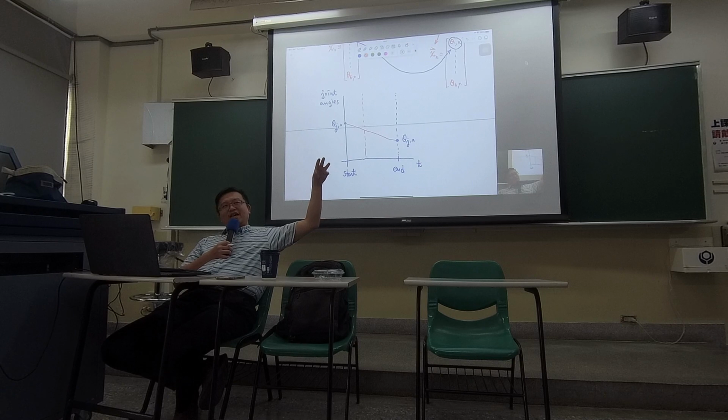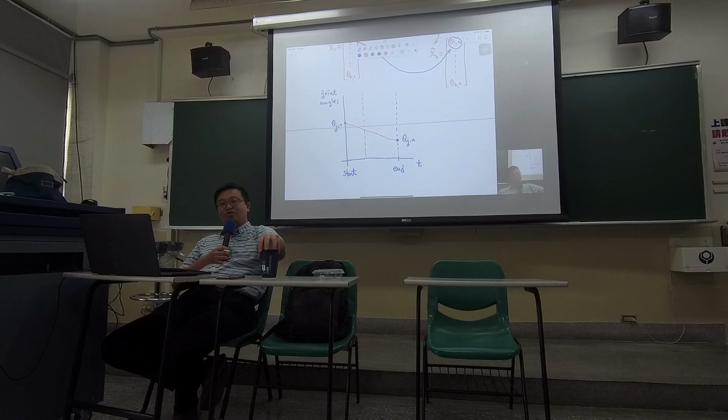What you get at the end is some kind of curvy motion. It's gonna be a curvy motion. And you have no idea where the end vector is gonna be, unless you truly compute the end vector coordinate at every intermediate configuration.